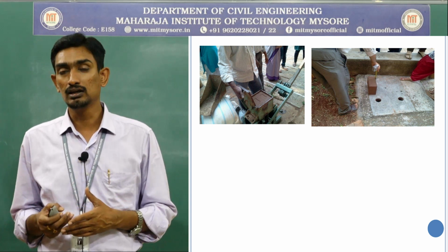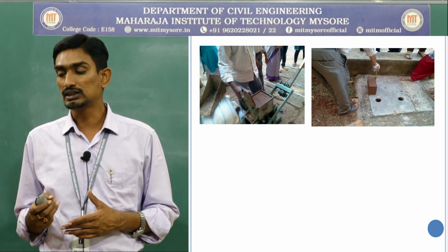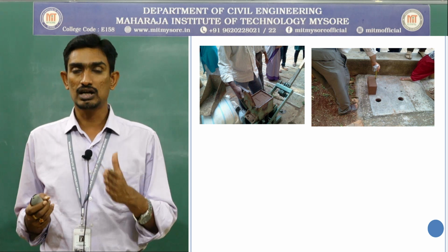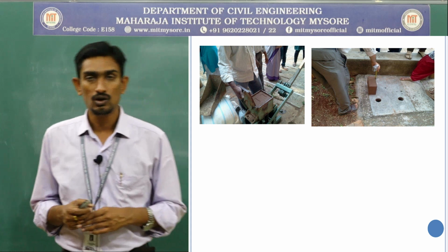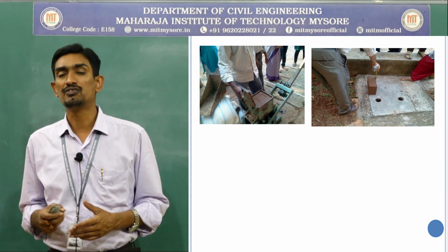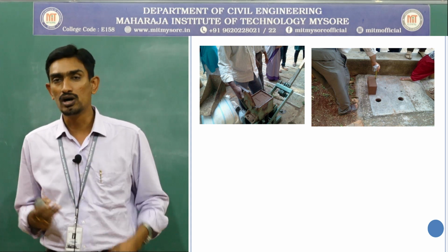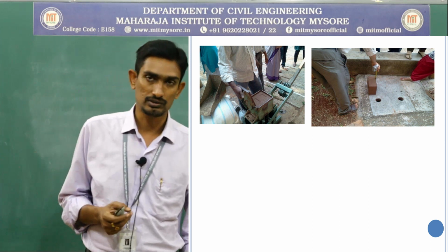Keep it for drying. He is checking the size of the block, whether it has attained the required shape and size or not. Then allow it to cure for 21 days and then go ahead with the construction process.